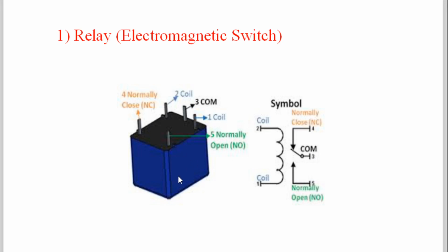So you remember one thing, there is one logic to remember. Wherever you find 3 terminals in one line, or the center terminal is a little bit away from the other 2 terminals, in that 3 terminals, the last 2 terminals are the terminals of relay coil.